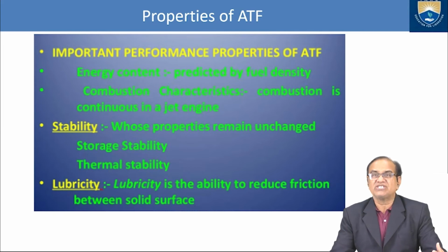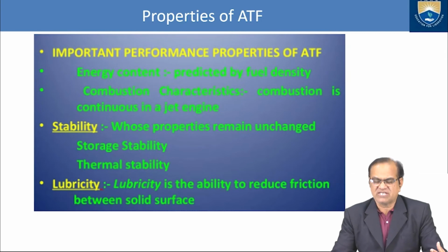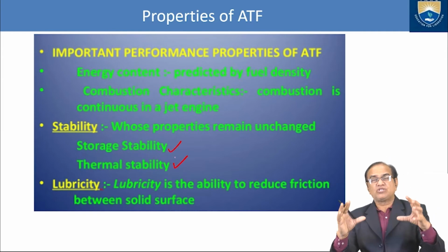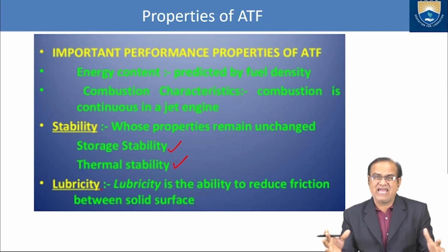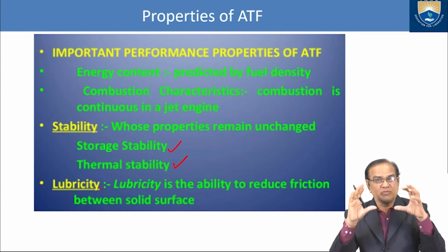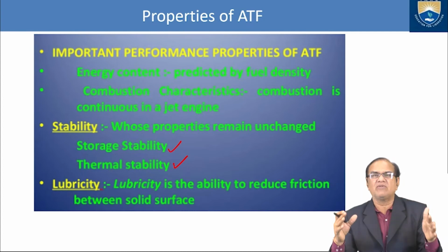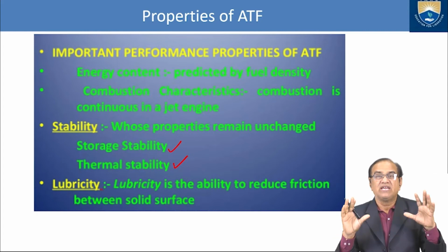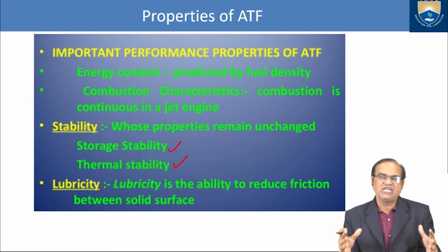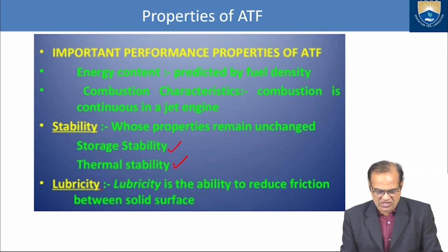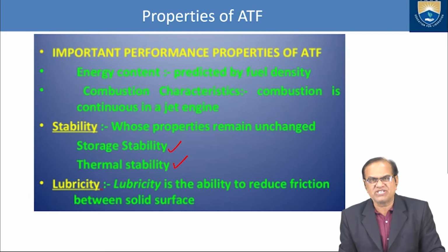Next important topic is stability, whose properties remain unchanged: storage stability and thermal stability. Storage and thermal means once you are keeping it in the tank, it should not deteriorate. It should not chemically decompose. It should maintain the same density over a long time of storage. Thermal stability: at different atmospheric temperatures, it should maintain its density, its combustion properties and its energy constant.